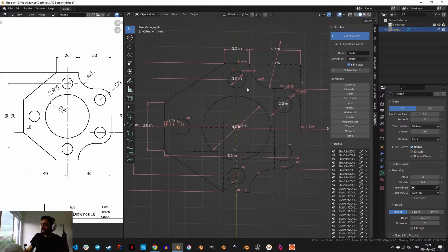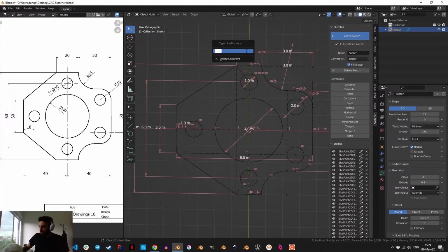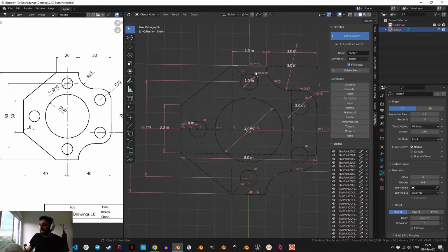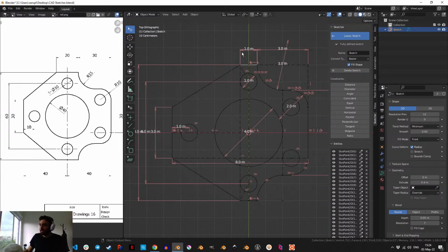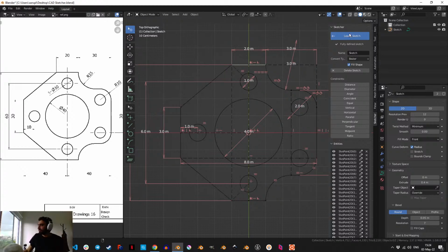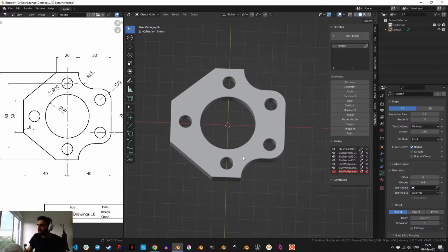So see how interesting this is. It was originally at 2 degrees, and this angle is actually figured out by the solver. And if I change it to 1 meter, then the solver has to change this line and make it more pointy in order to match all the other measurements. So that is the power of parametric design. All right.